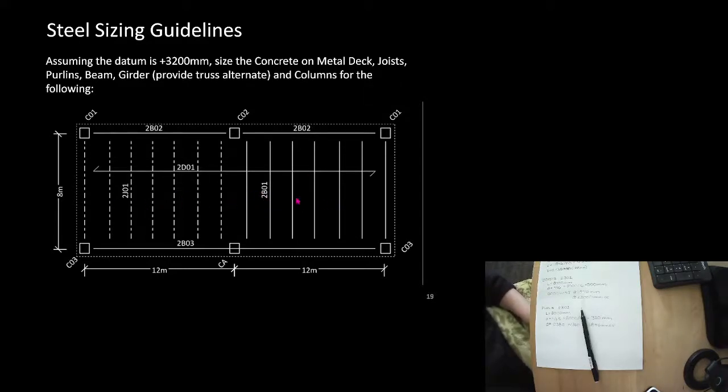Look at this. We had the two things doing the exact same job. I told you that beams tend to be the beams that support open web steel joists and purlins. So look at this. These span to this side and this side. So this side and this side support these purlins and open web steel joists. But there's no columns underneath them, so the beam spans from here to here.